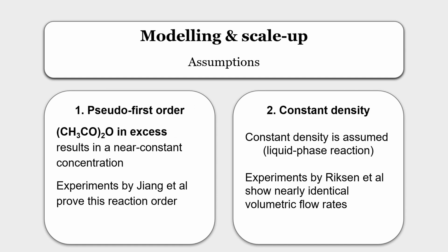These are key assumptions for scale-up. First, by excess input of acetic anhydride, we will induce a pseudo first-order reaction. The evidence of it will be given later. Second, because the reaction is in the liquid phase, we can assume constant density and volumetric flow rates.